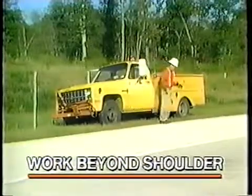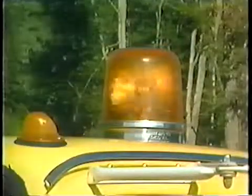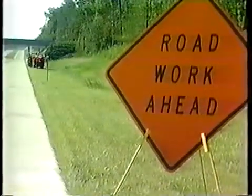In the first example, the work is entirely beyond the shoulder or parking lane. Traffic control will generally consist of flashing vehicle lights and flags. An advance warning sign should be used when the work will interfere with traffic in any way.